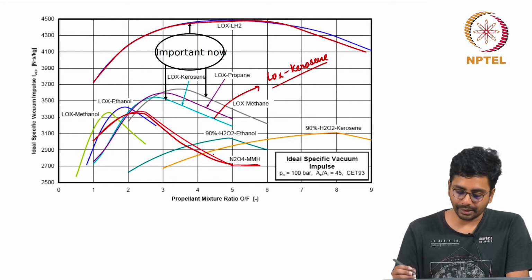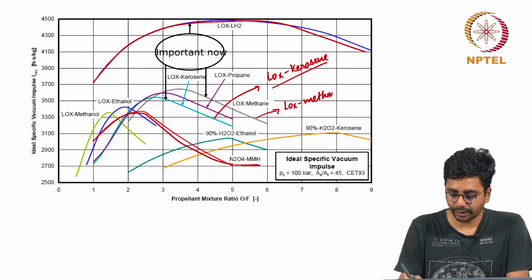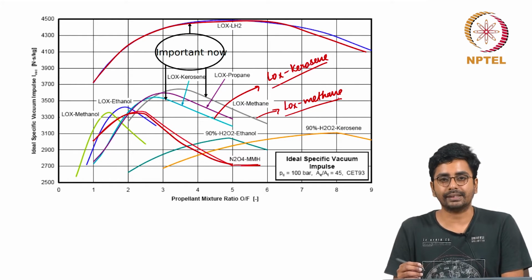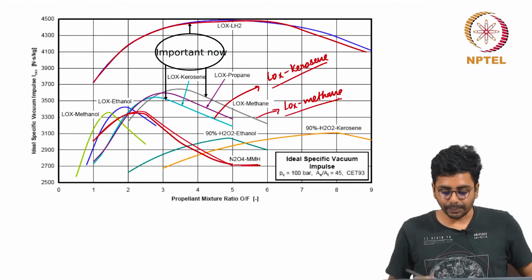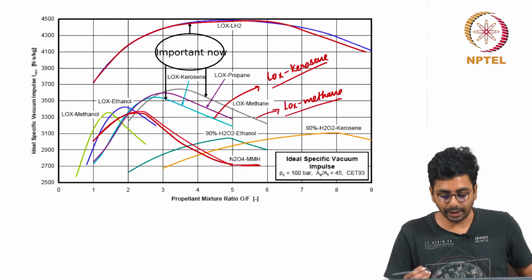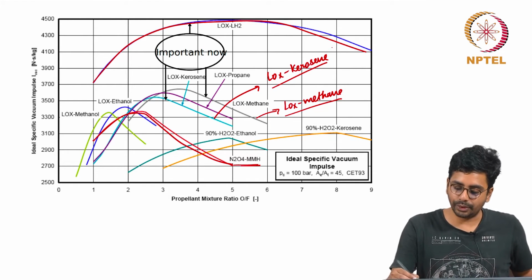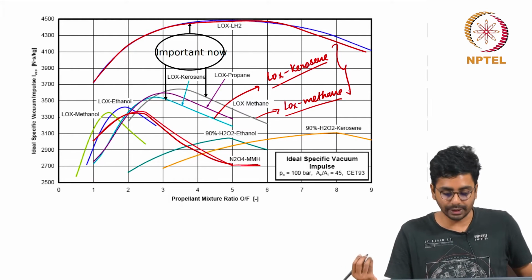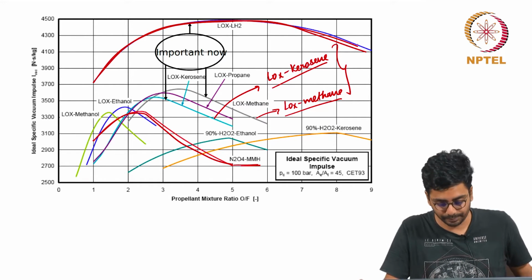and another emerging technology is the LOX methane system. As you can see, it has a slightly higher specific impulse than the LOX kerosene system, and again is being contemplated as a high thrust booster for the first stage. So the choice is very simple. Small rockets use earth storable propellant with hypergolic ignition. Large rockets requiring a large takeoff thrust should use LOX kerosene, LOX methane systems along with solid strap-on boosters. Long missions should use cryogenic systems.